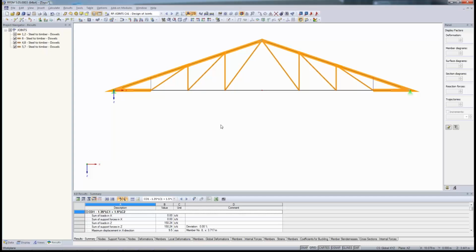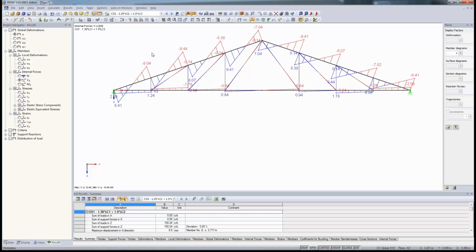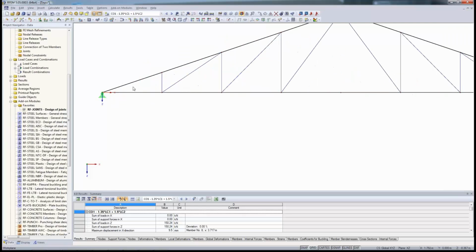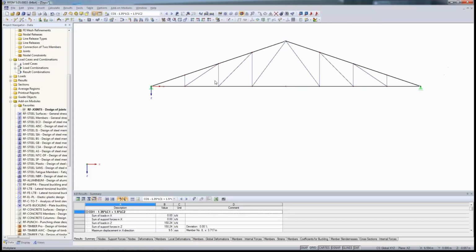Okay, to export the stiffness calculated by the module, I have to change something in my modeling. When we started the modeling of the structure, we defined moment hinges here and also truss beams that have a moment hinge. Now if the module designs the stiffness, we have to make it rigid before, otherwise it won't work.